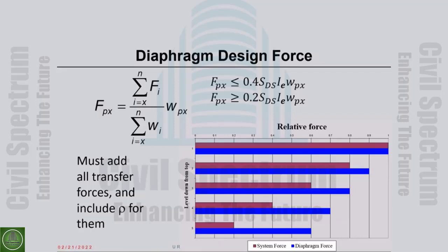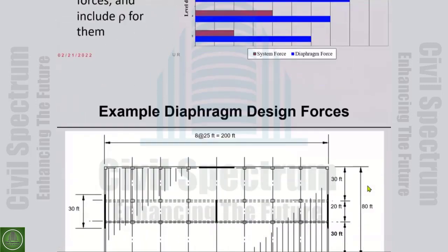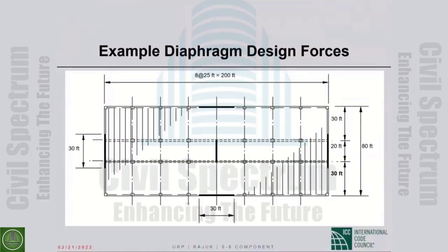Okay, diaphragms are much more susceptible to higher mode effects. And those effects will impose higher forces on the diaphragms. Anyway, that formula we have used for a long time, and that gives you the diaphragm design force distribution as shown in the picture. I will do an example here. I didn't try to change the units in view of comments made on earlier occasions. I think most of you are at home with the American units, so I left it the way we had it. Okay?